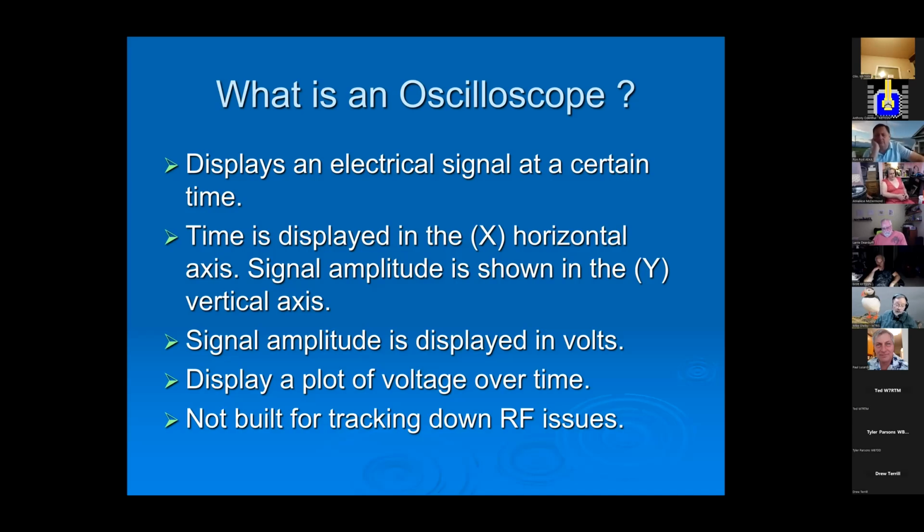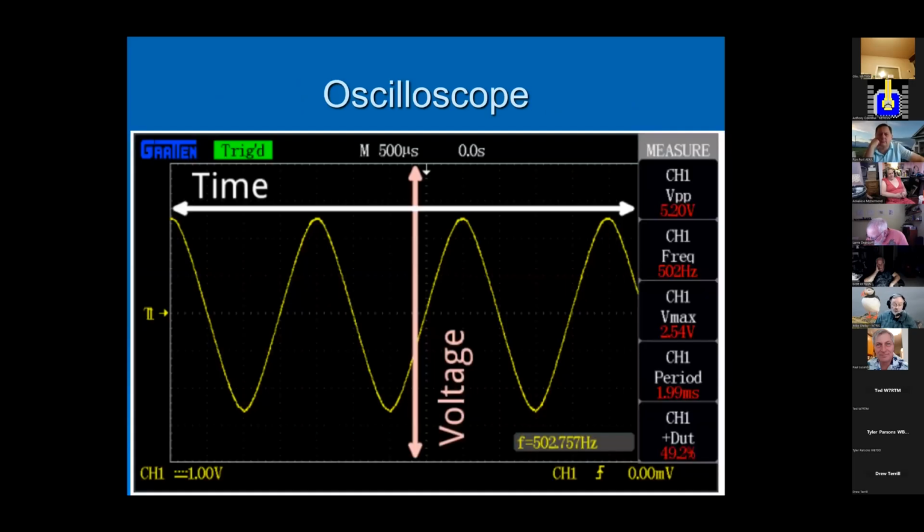So it actually displays a plot of voltage over time. Whatever signal you're looking at, it displays whatever that voltage is over some amount of time, whatever that sweep time. So understand, this guy here is really not built for trying to track down RF issues, radio frequency issues.